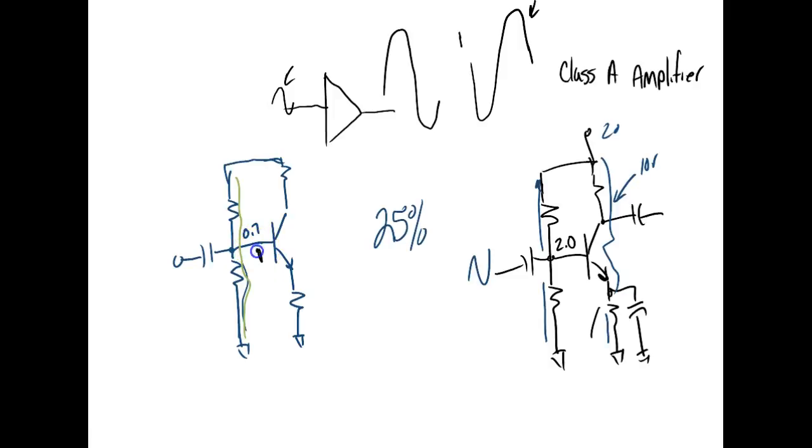If that's at 0.7 volts, what would be my voltage right here? What'd you say, 0? How much current flow do I have over on the power side? If this resistor right here is dropping 0 volts, how much current flows through it? 0. So that means my power side right now is consuming no power at all without an input signal.